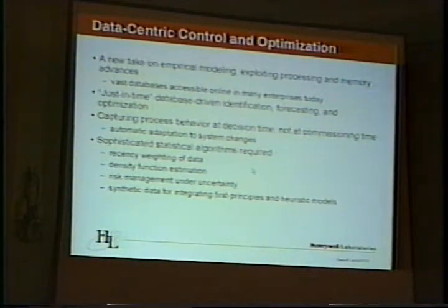But one point to note is this last bullet here, that in fact this data-centric view also provides you a multi-modeling approach as well, because if you think about accessing a database to get all your data for doing any predictions, your database doesn't have to be populated by real data from the plant. It can also be populated by data that's generated by exercising first principles models and heuristic models. So in addition to having a conventional maximum likelihood kind of framework for this, you can even incorporate a Bayesian framework by taking into account first principles understanding through exercising that first principles model with various relevant inputs.